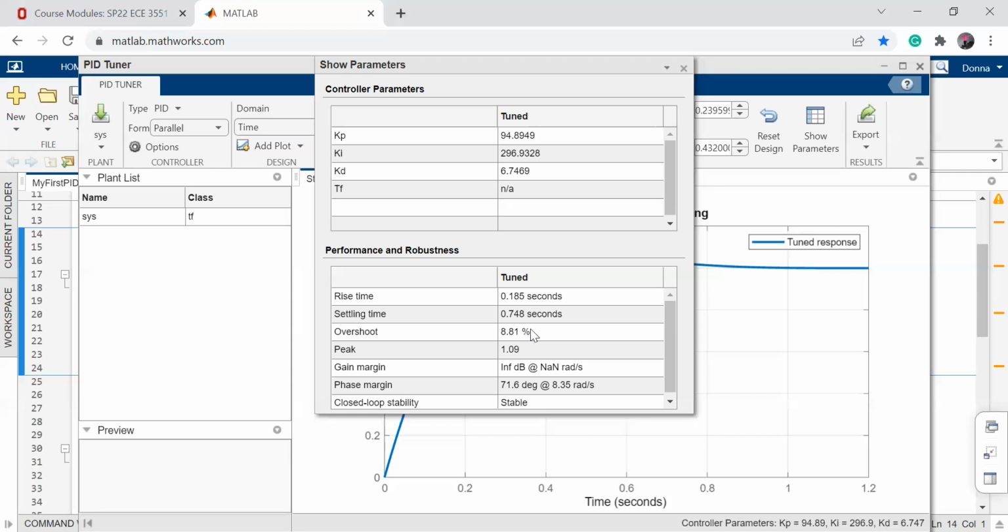So first, we are not living in an ideal world. Second, do you remember system sensitivity? There might be something in the system that makes it sensitive. So if in your system's environment there's a little bit of noise, you can throw it off, right? So that 60 hertz might not be 60, like you're having something like 65, just because there was some noise in the environment, let's say. Here the same. There might be something from the environment or some of the linearization you have done, right? All of these are estimation, like this transfer function we write, you're making a nonlinear system linear, right? They're all LTI, agreed? Most systems are nonlinear. So we are estimating.